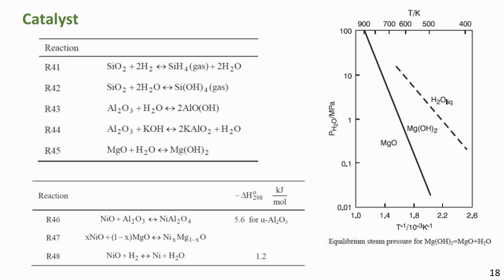degrees C. Kinetic studies of the hydration reaction have shown that magnesia reacts via a liquid phase reaction in which water condenses in the pores. Therefore, the rate depends on the relative humidity of the atmosphere, and in practice, hydration is a problem only when the magnesia-based catalyst is exposed to liquid water or is operated close to the condensation temperature.